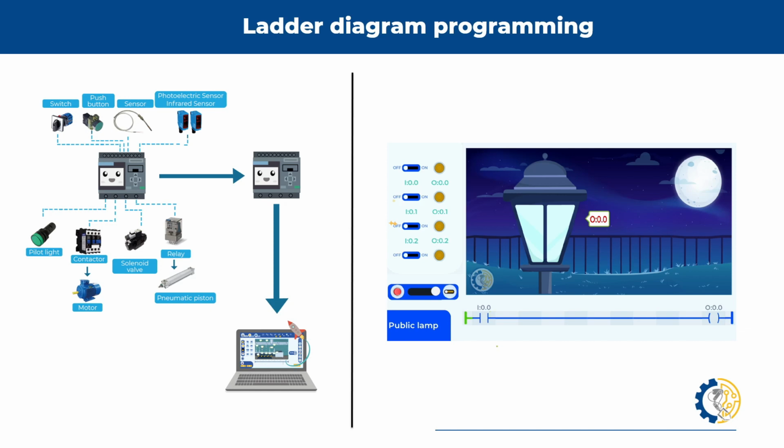Everything that we're looking at here on the top part is a simulation. It's within our Animator PLC. This is a selector. We can change it through push button or selector. I changed it to selector so that we can really continue simulating through this device with our Animator PLC. So again, I power it on, I allow the flow for the signal, and power on the lamp. So again, it allows flow, and that's all that the ladder diagram does.